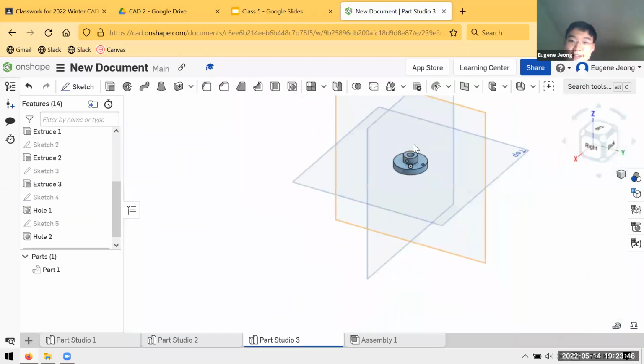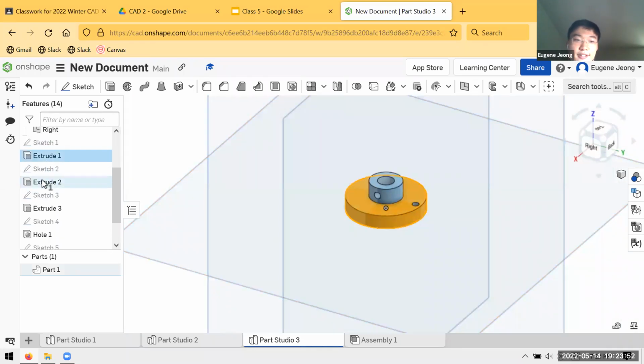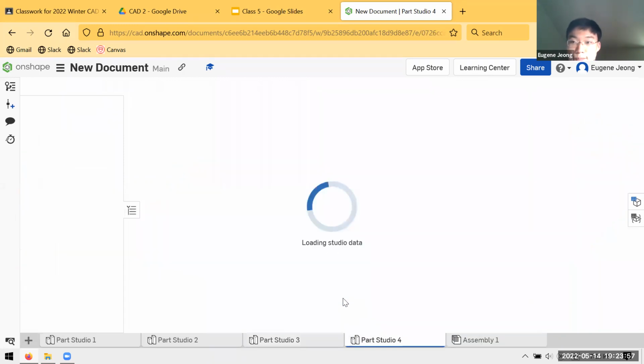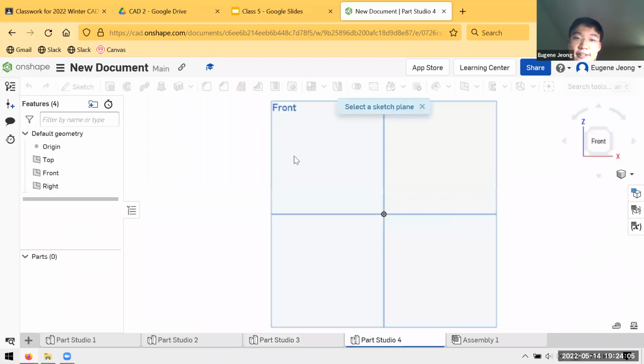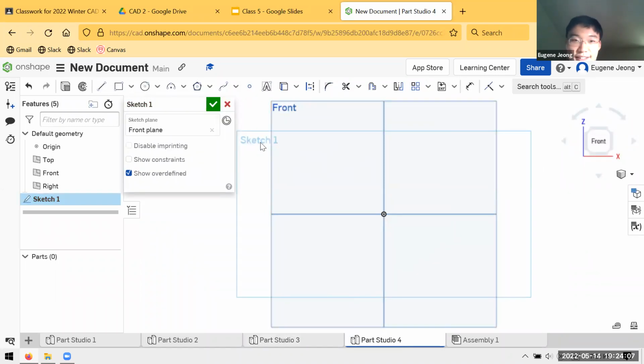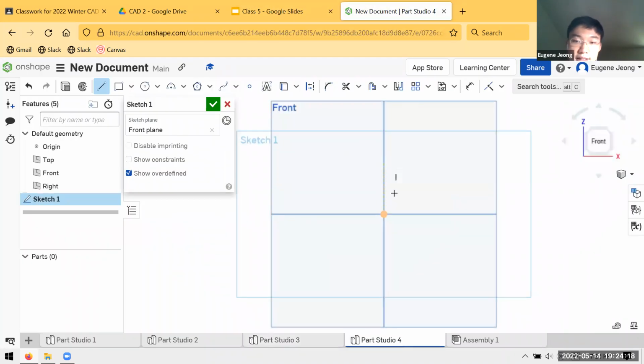Since we're recording, for those of you who are curious, I can show you how you can do these three features all at once using the revolve. Depending on the context, this may or may not be a better or cleaner way to do it, but it does reduce the feature count. What's most important is context, like what you're most likely going to change if you were to edit this feature. So really, who's to say whether or not this is the better way to do it, but it is another working way to do it.